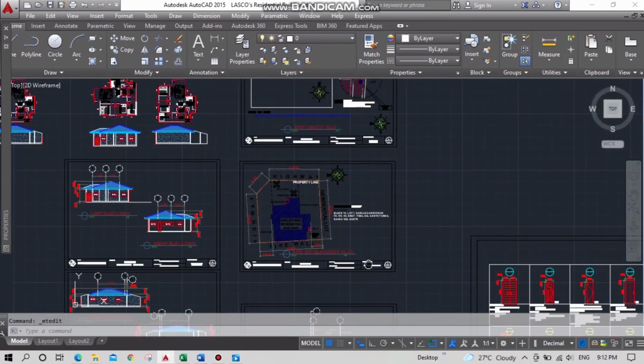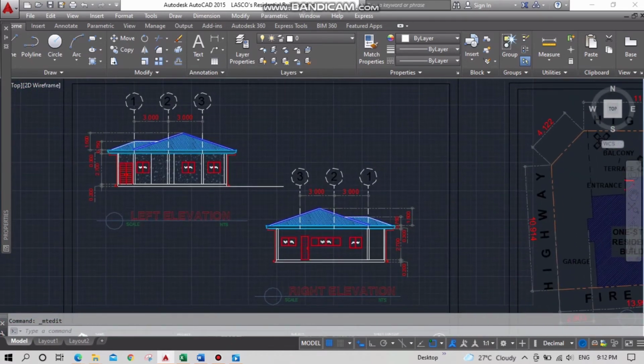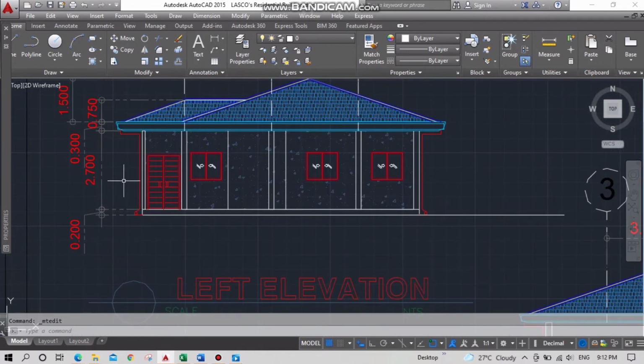So, the ceiling heights is makikita dito sa elevations. So, for the elevations, sabi dito sa National Building Code is that habitable rooms provided with artificial ventilation have ceiling heights not less than 2.4 meters measured from the floor to the ceiling. So, ito dito is 2.7 meters man ito. So, greater than 2.4. Therefore, okay siya yung ceiling heights namin.